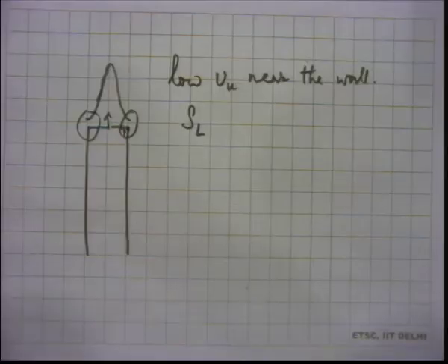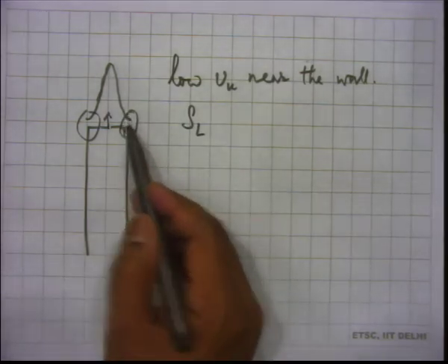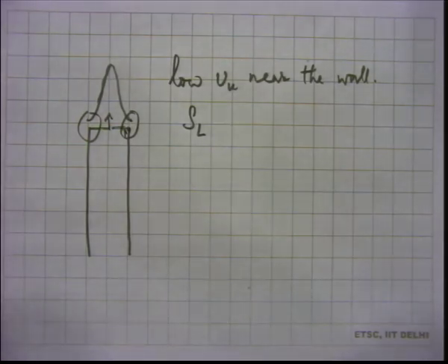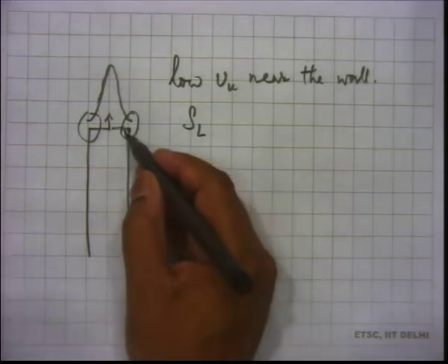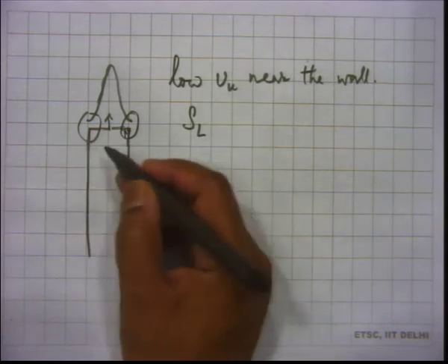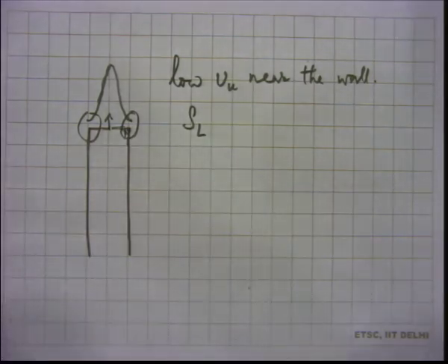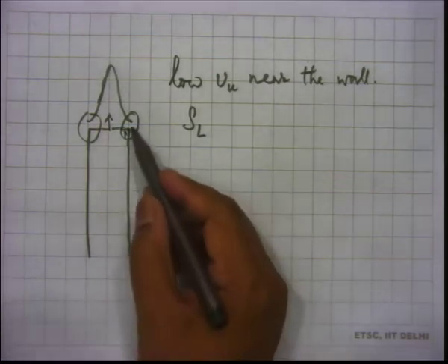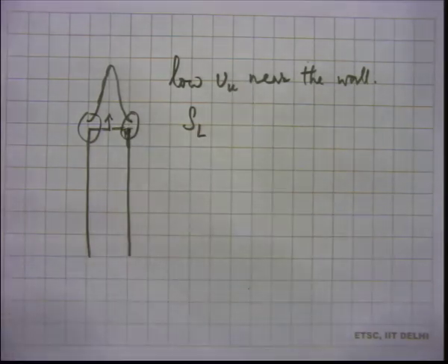But here you have a mixture giving you a flame which has its base very close to the top of the burner. So it will lose a significant amount of heat to the solid of the tube. If you measure the tube temperature in this region, you will see higher temperatures. If you are doing the experiment at room temperature, maybe 300 Kelvin, it's possible that the temperature in this area becomes 310, 320.